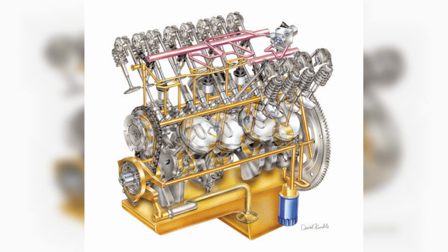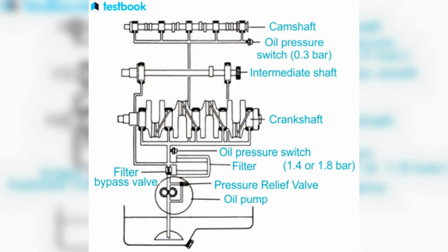When the ignition is turned on, the oil pump is started, designed to create pressure and pump fluid into the channels, which were empty during the parking of the car. It takes a few seconds, and that's how long the light for insufficient pressure in the lubrication system is on. Once the pump is running, oil from the sump starts to flow to the oil filter, then to lubricate the crankshaft bearings, connecting rod and main journals and camshaft,